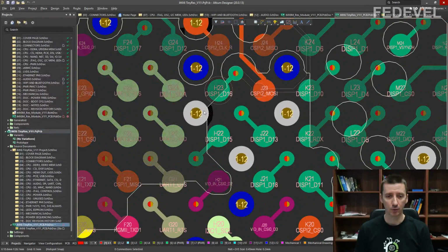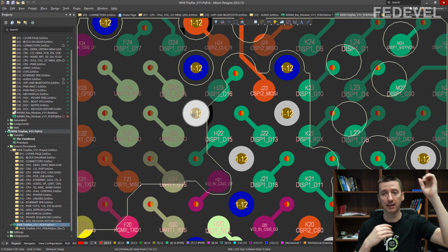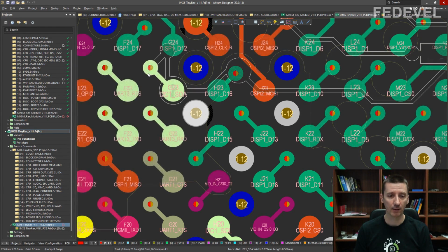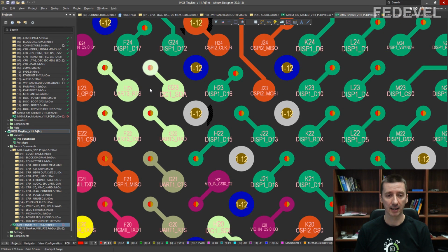We are speaking about through-hole vias. Don't forget, when I'm speaking about via here in this design, it is the same as, or we can use the same kind of via also as via in pad. So imagine this as via in pad from top and bottom layer in our new design. And then we have also these smaller vias, and these are microvias.